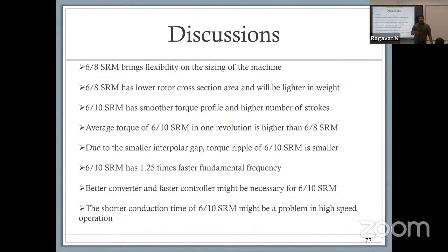I cannot change torque ripple by just controlling power electronics. But in power electronics, I can get a faster switch. I can get a faster device. I can have a much better bandwidth with better resolution in my sensor. So the understanding was power electronics is advancing at a much faster rate than the machine physics and electromagnetics allow. So that's why the shifting of the complexity was, in our view, a very important step in the right direction. So I'll actually show you at the very end.